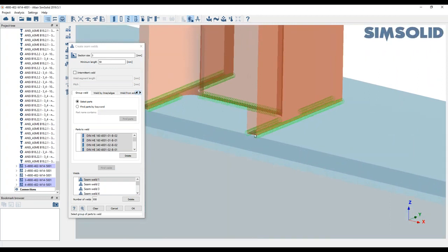It basically creates an edge of that vertical plate and creates a contact with the horizontal beam. Inside Nastran, for example, what would have happened is it would have created a face contact of that plate with a face contact of the horizontal beam, which is not strictly speaking correct, but obviously that's how it works. I think it's a pretty big task to suppress all of them and then reconnect the edge with the faces of the beams.